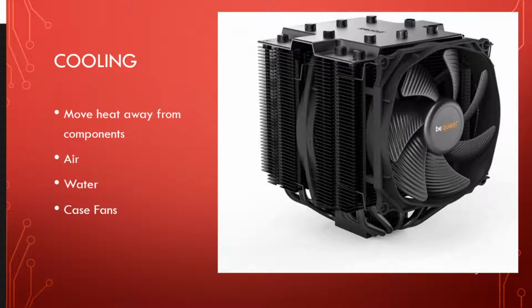That CPU is not going to be perfectly flat. And your cooler probably isn't perfectly flat. So that's why we have that thermal paste. It's to help take up those irregularities and allow heat to transfer between the two more consistently. So put some thermal paste down, slap this cooler on top, screw it down so there's a specific amount of tension. Normally there are screws or springs that keep it having the right amount of tension, and that allows the heat to go through heat pipes up into the cooling fins.